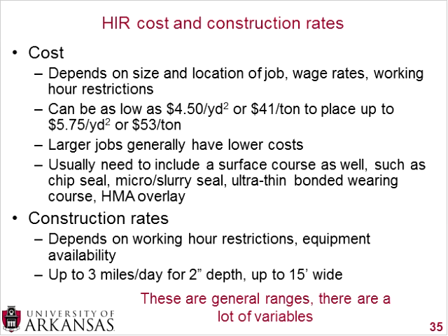So the final slide here of technical content is your cost and your rate of construction that you could do. And got to put this disclaimer here at the very beginning. The cost is highly dependent on the size and location of the job. Obviously, with larger jobs, the cost will go down a little bit. A location of a job closer to the contractor or closer to where a lot of the equipment you're using is, that will drive down the cost. And it depends on wage rates and also if there's any sort of working hour restrictions.